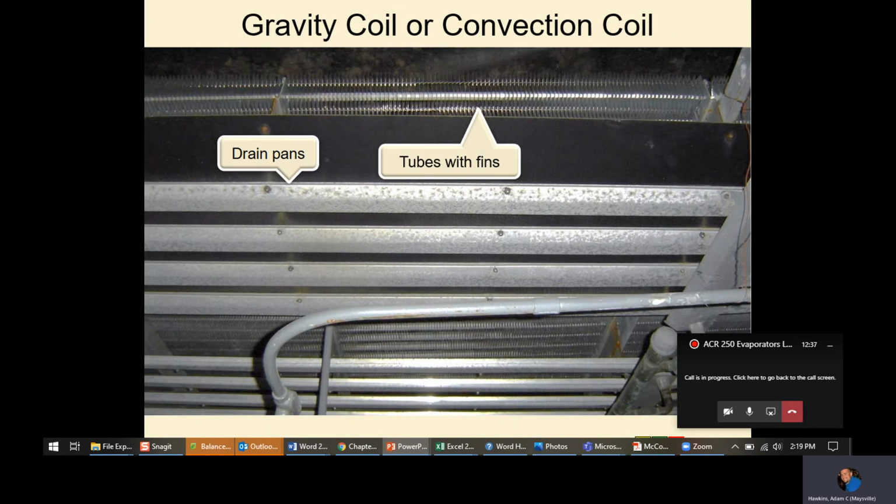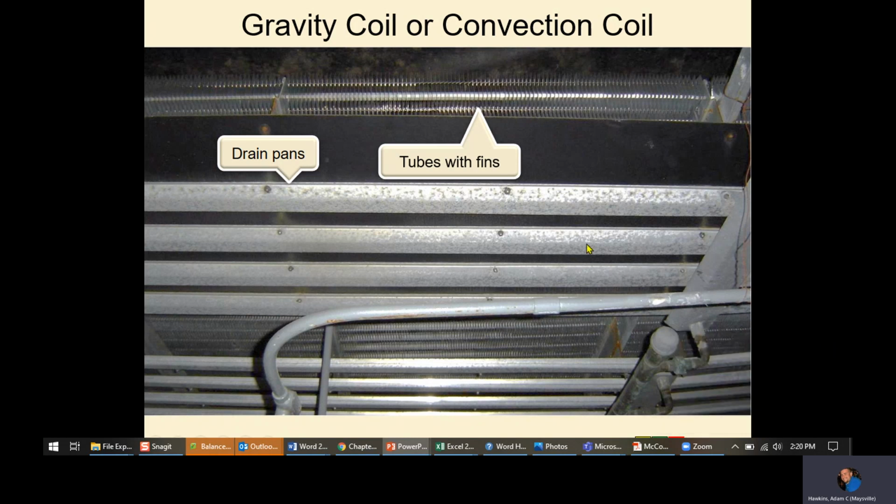They increase the surface area that's colder, but they also slow down the air. So those fins, they're not just a straight shot. A lot of times they're made in such a way that the air has to work its way through them. And by doing that, you allow what we call dwell time. And dwell time is just how long the air has across the evaporator.